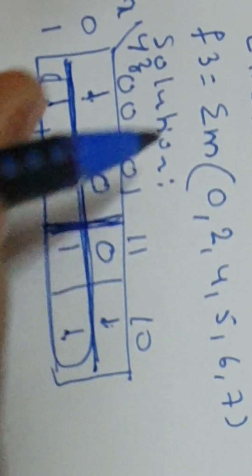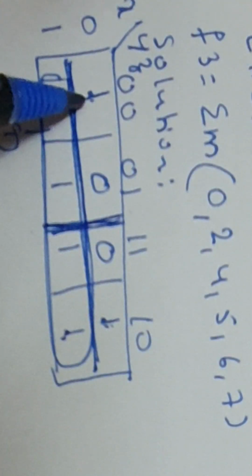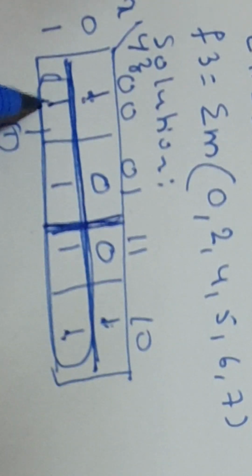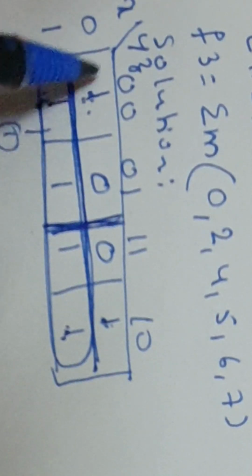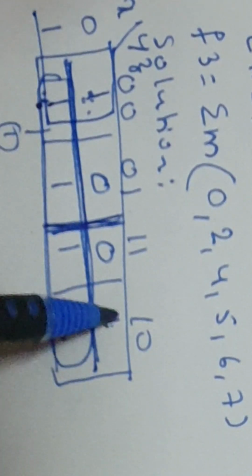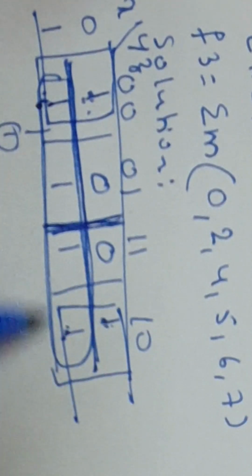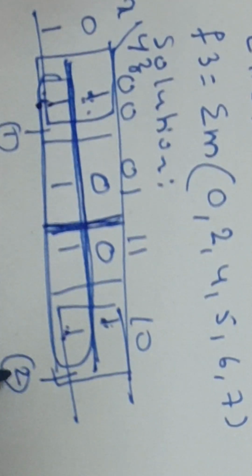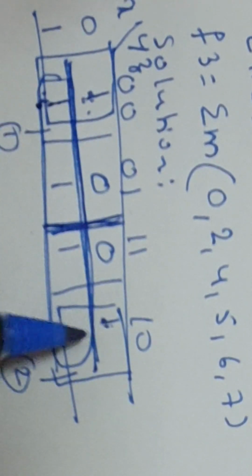Next, on this line, if you fold again, all fall on one square. Hence 1, 2, 3, 4, they make only one group, that is a quad group. So that is grouped as the second quad. This is the second group, a quad having 4 members, 1, 2, 3, 4.